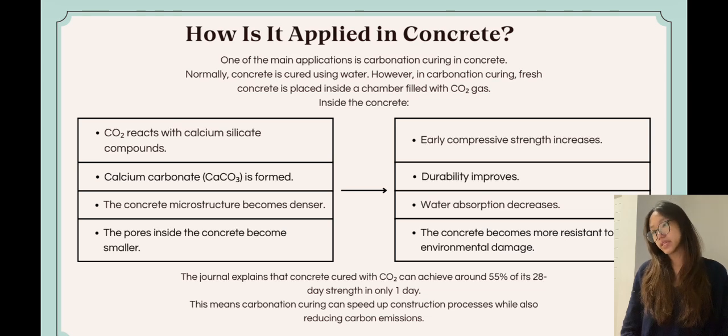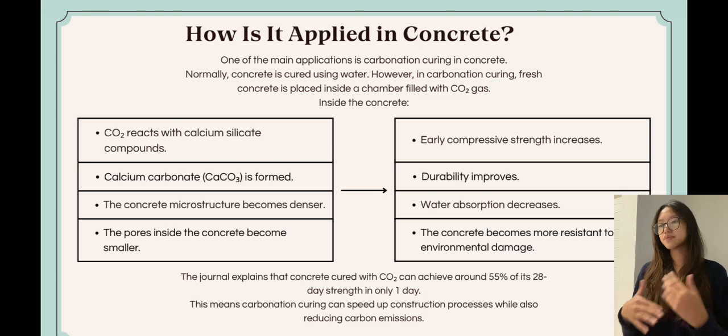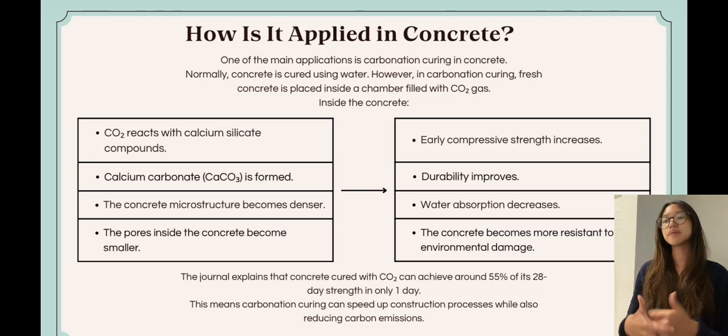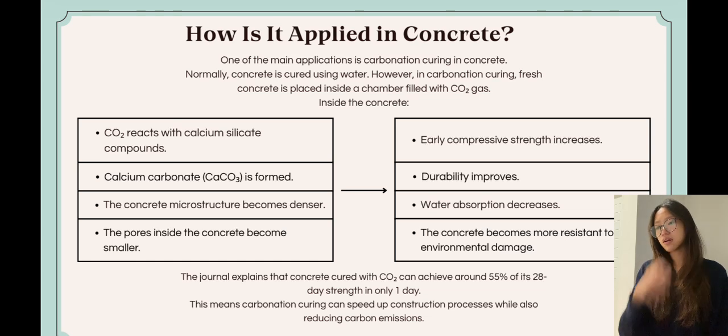Inside the concrete, the carbon dioxide reacts with calcium silicate compounds, and calcium carbonate is formed. The concrete microstructure becomes denser, and the pores inside the concrete become smaller. The result is that early compressive strength increases, durability improves, water absorption decreases, and the concrete becomes more resistant to environmental damage.